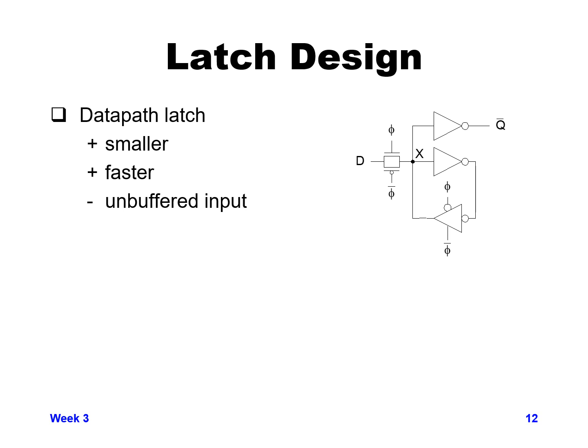If you don't know what is driving into this latch, it could cause problems. But as long as you know where you're using it and what is driving into it, you could be okay with this type of design and get a faster, smaller device out.